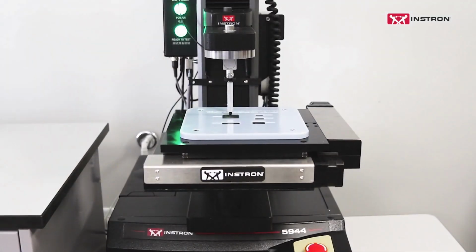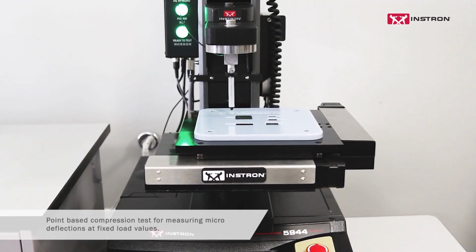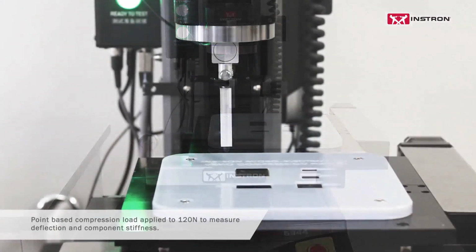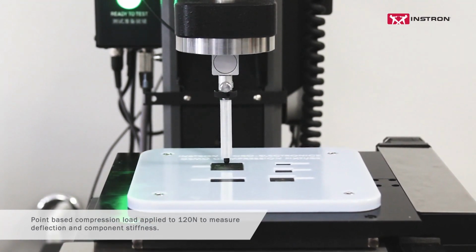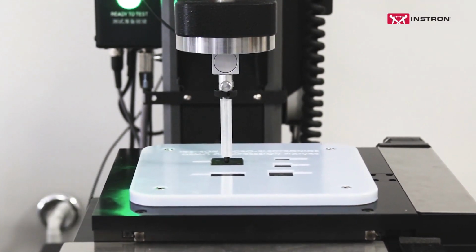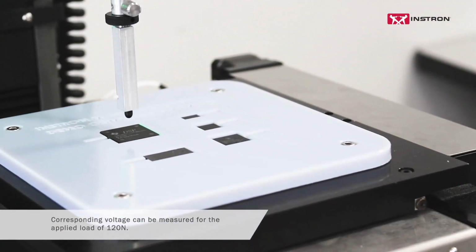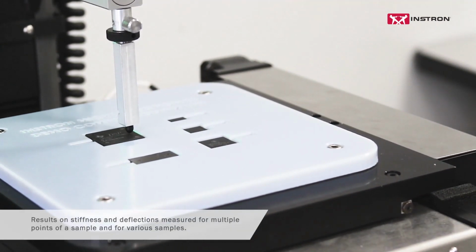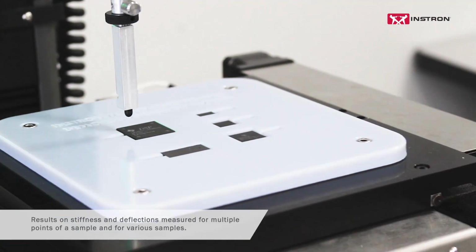The materials that are used to manufacture integrated circuits, they're rapidly evolving. So here it's being tested in a diamond pattern. The chip is loaded in the center and then at 3 points around the edge. At each point, it's loaded with a compressive load of 120 newtons, that helps measure component deflection and stiffness, and the corresponding voltage is also measured and stored. So the stiffness and voltage data can be used to compare various chips and to qualify new materials and forms for electronics packages.